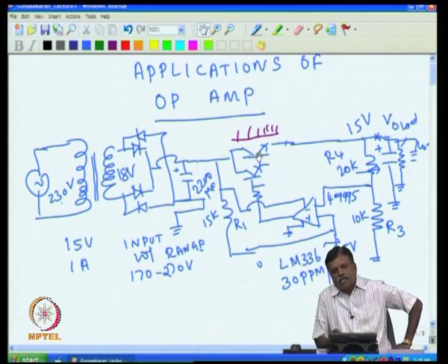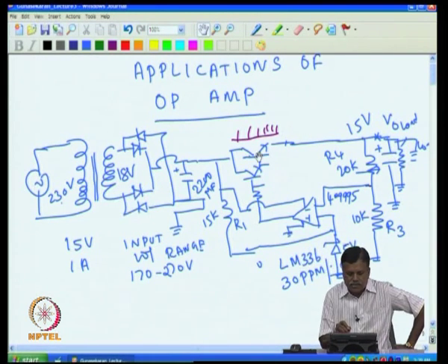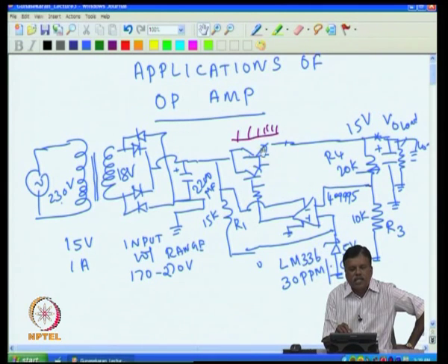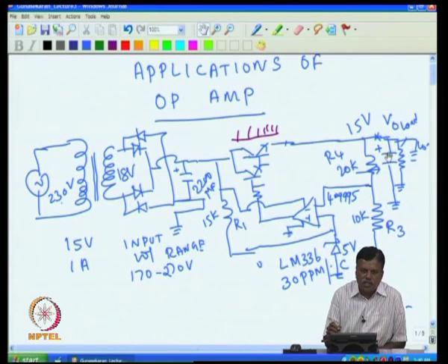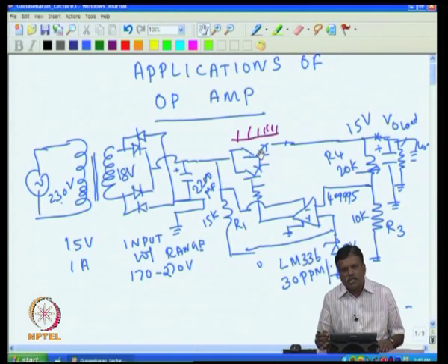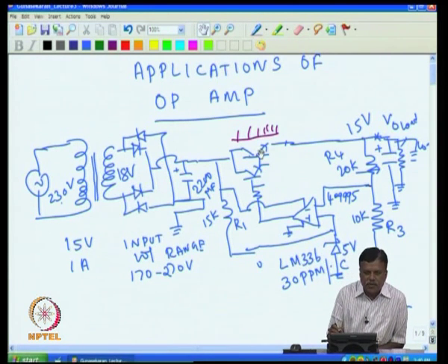This is a very important thing for any circuit designer, particularly for voltage regulator. This is very important, because the voltage regulator is the critical part of the equipment where most of the heating is taking place, and that decides the life of the equipment, because if the voltage regulator fails, then the whole equipment fails. So, depending upon the junction temperature, I have to decide the heat sink. Assume that I want a life of say 1 lakh thermal cycles, then I want to keep the junction at say 100 degree C. Then assuming that, let us design the heat sink now.